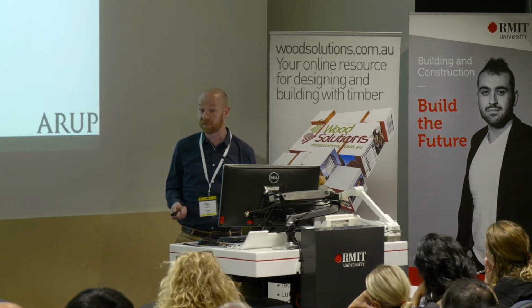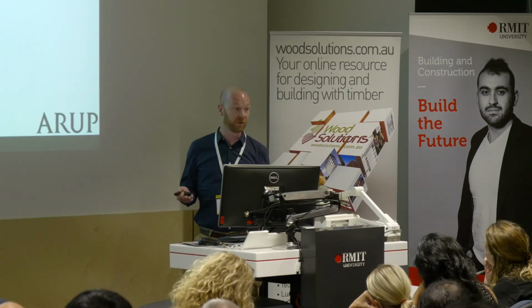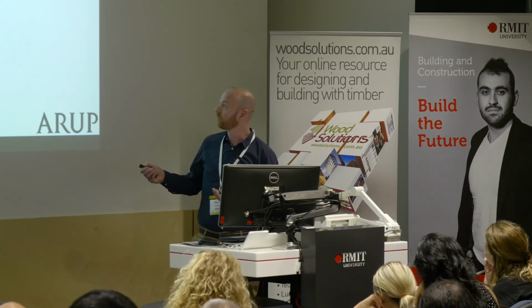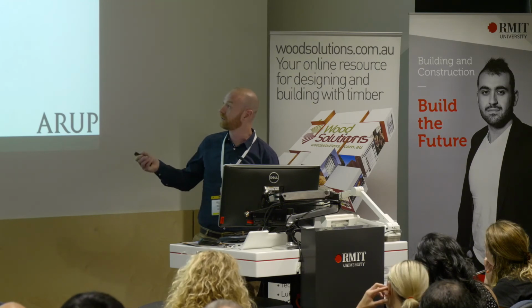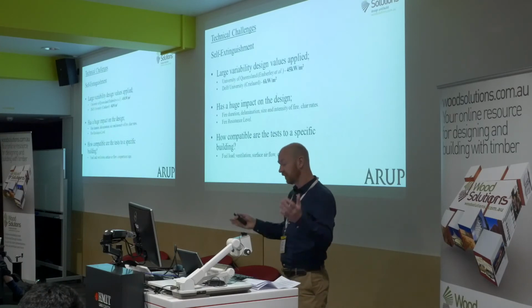Now in terms of building design, particularly for exposed structure, if your timber's still smouldering, it's still burning, you're still losing fire resistance out of your building. So we would much prefer to see self-extinguishment limits in this region. And what's the impact of that? It's a huge impact.